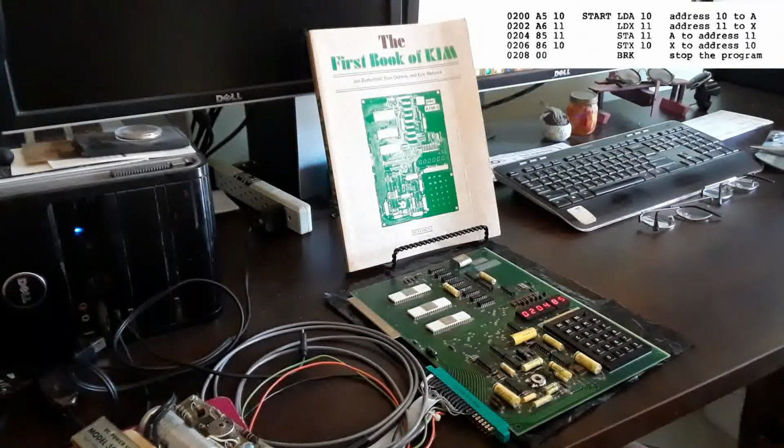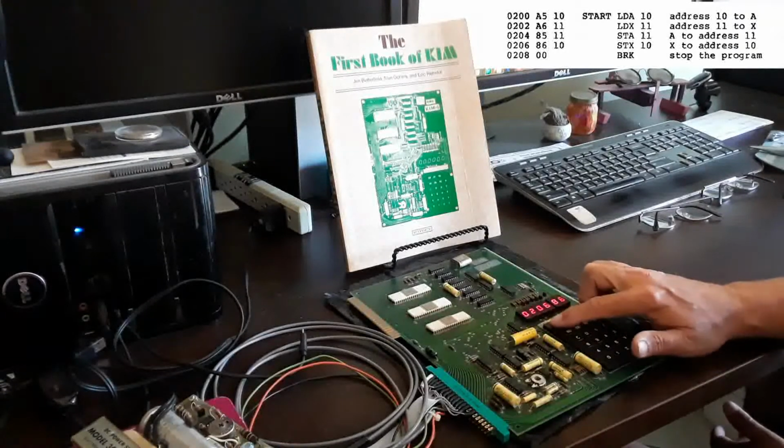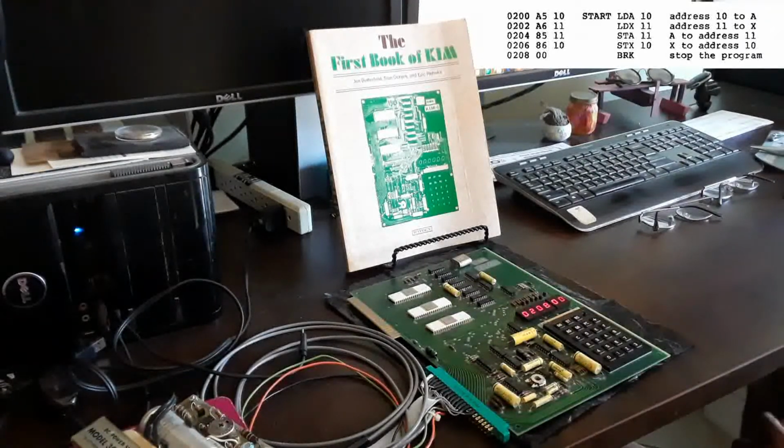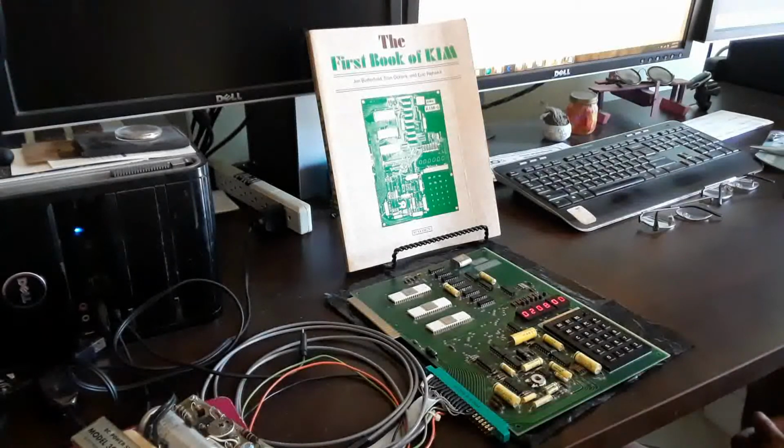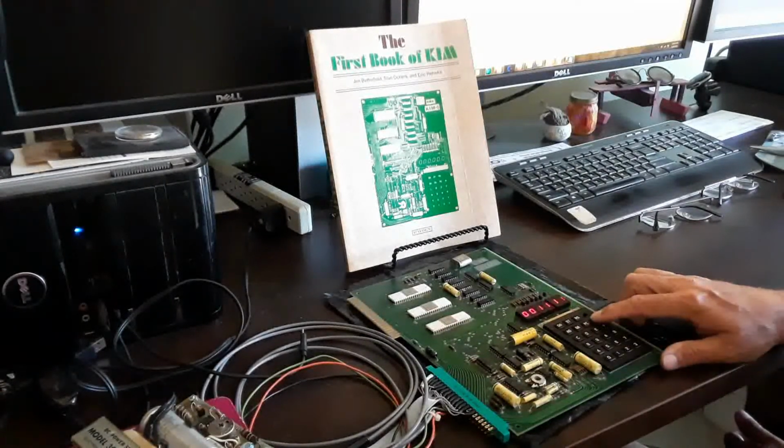When we press go again, it will advance through the next step of our program, which is STA 11, where we will store the contents of the A register into address 0011. Now we will go ahead and single step through the final opcode, STX 10, which will copy the contents of the X register into memory location 10. So now when we look at the memory addresses at 0010, it now contains the new value that we had placed in the memory address 0011, and the memory address 0011 now contains the value that we had set up in memory address 0010. There's our 99 and our 11.